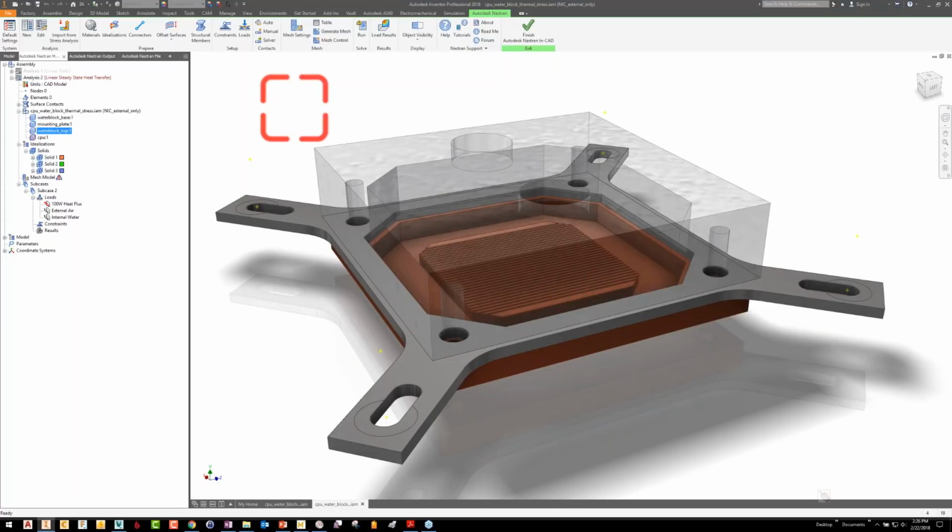It determines an appropriate size for those individual elements based on the CAD geometry, or at least it's usually appropriate. It tends to do a pretty good job of that default mesh successfully meshing and successfully running. But it's by no means the last that you'll see of that mesh. The default mesh tends to be coarse. It does affect the results, and they can be improved by refining the mesh, and you're going to want to.